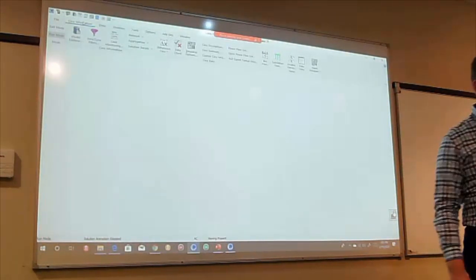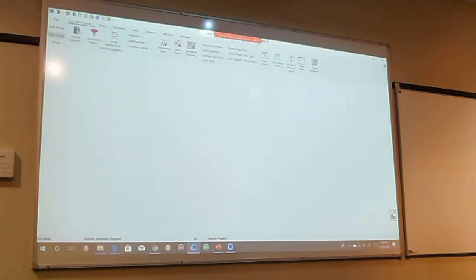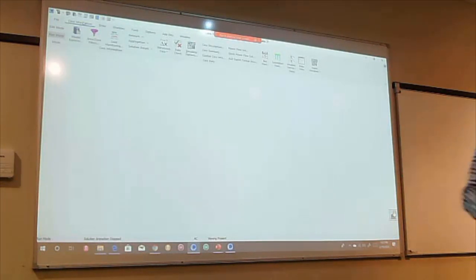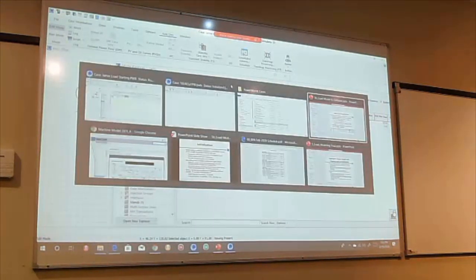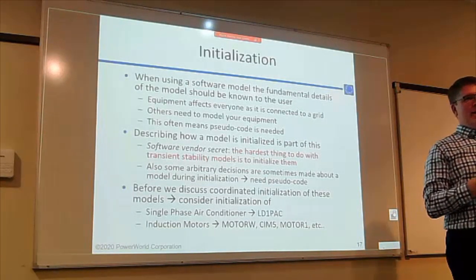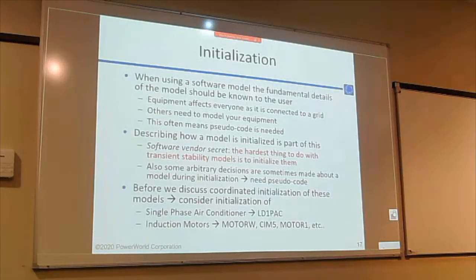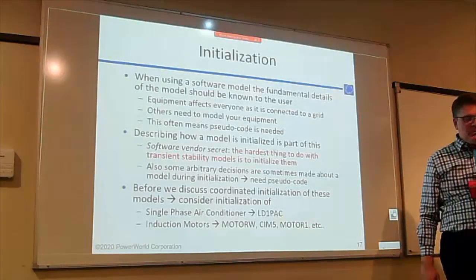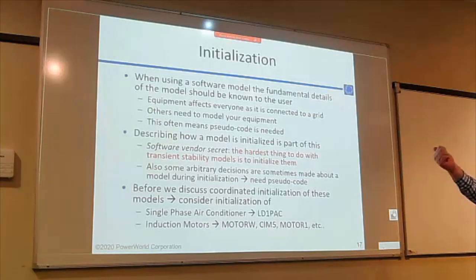There was a paper in 2012 where you can convert those to zip models to get a more accurate steady state assumption. We haven't implemented that. There was a 2015 paper presented at ESPS that did a really good job showing how to do that. That was 2012. Oh, wow. We're getting older. You've crossed where you used to be the youngest person in the room, and now you're in the upper half. James wrote the paper. He took the composite load models and ran transients and then curve-fit all of the zip models to the different components.